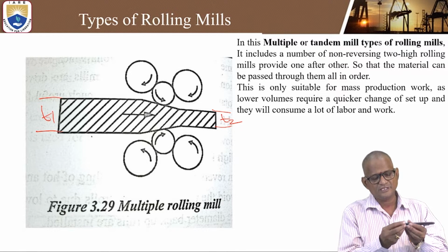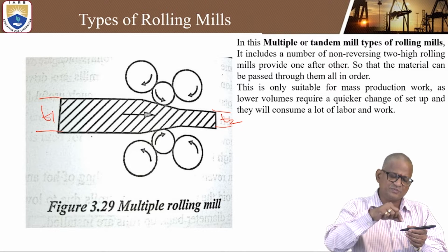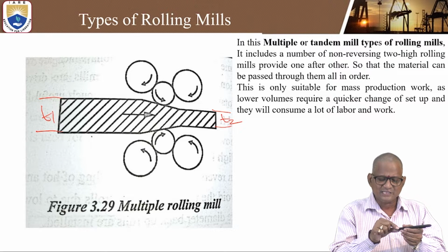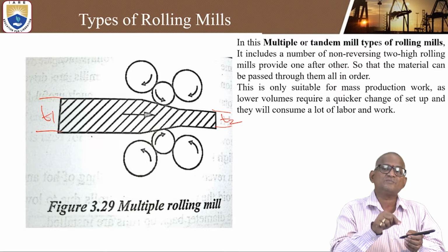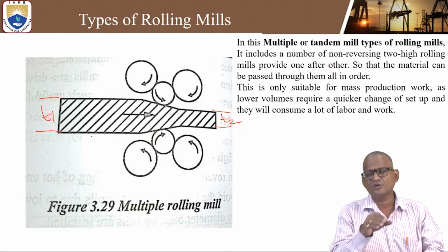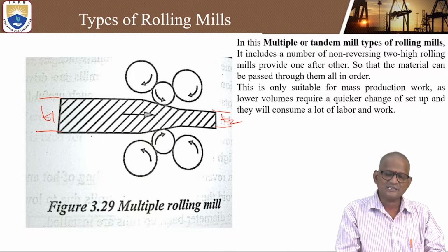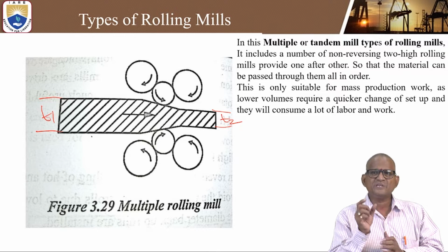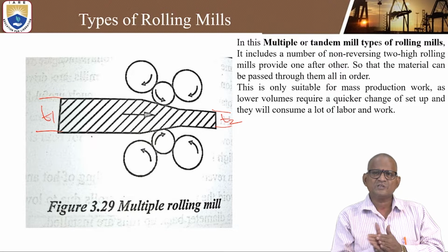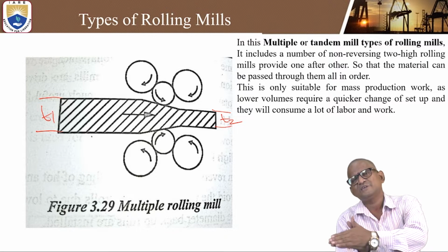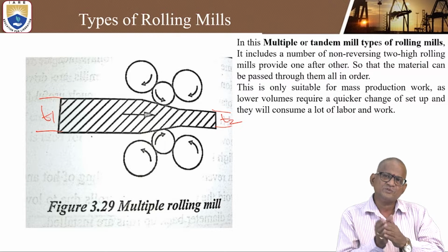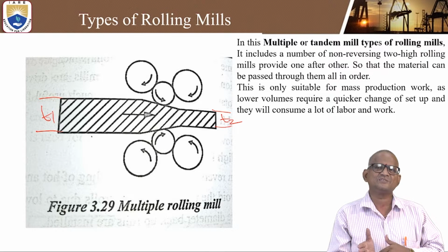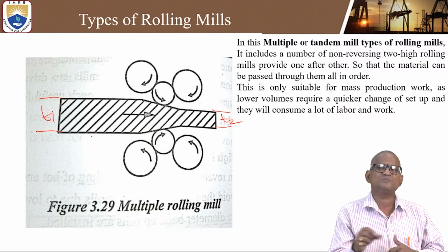Like you can see in this pen also, how much effort. This can also be done. First you can put a roller and put the backup roller so that the thickness is reduced by applying the compressive force slowly, and finally whatever thickness is needed can be obtained. And one more thing, the material is passed through them in order, one by one. Slowly you apply the raw material so that the reduction can be easily made. Otherwise, if you do it fast, the total overall thickness cannot be reduced.